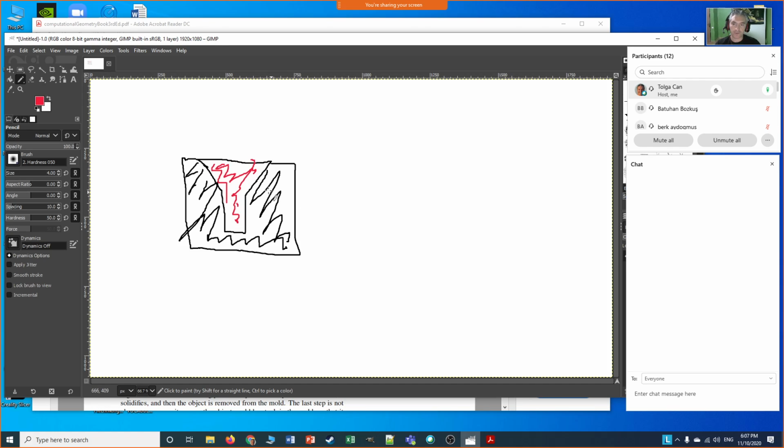One thing you can do is break the mold and get the plastic outside the mold. But we want to reuse the mold. We want to use this mold for multiple manufacturing of this thing, so we don't want to break it. One way to get this plastic out of the mold without breaking it is to pull it in some direction. After it solidifies, you just pull it out of the mold so that the mold can be reused by pouring in another melted plastic. So that's the problem.